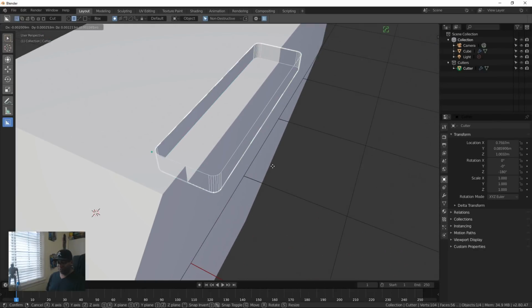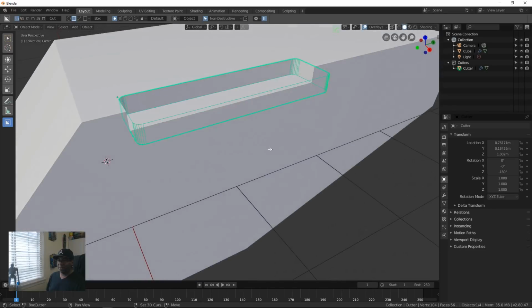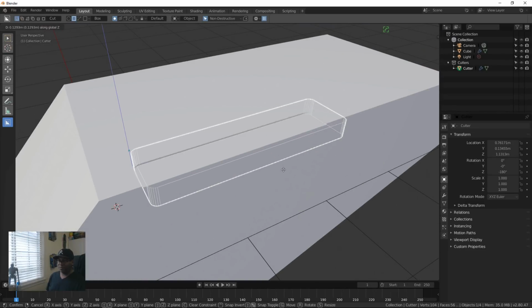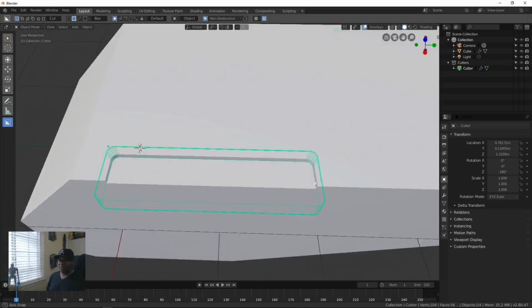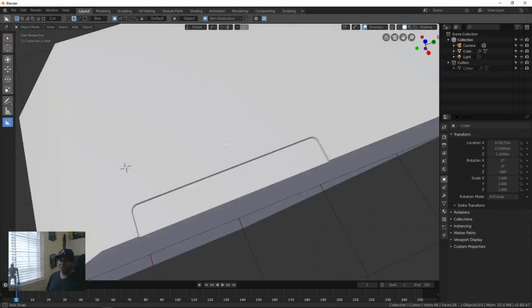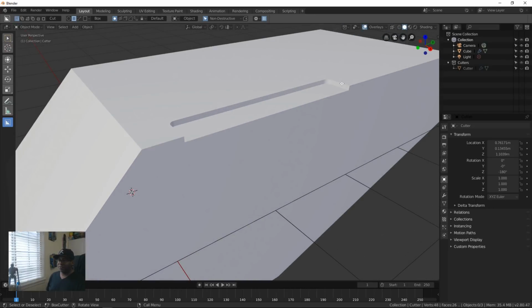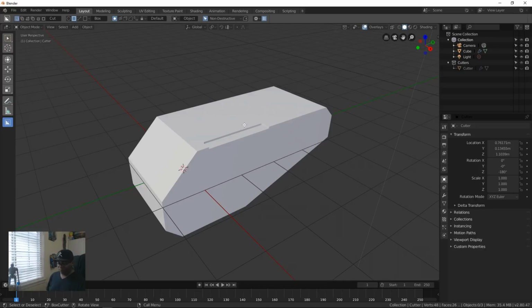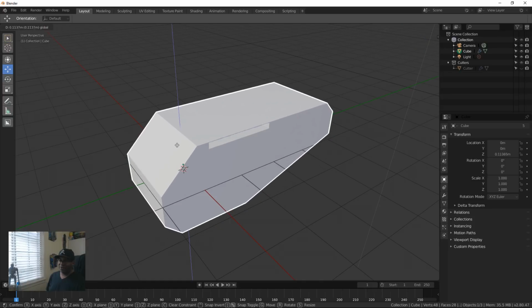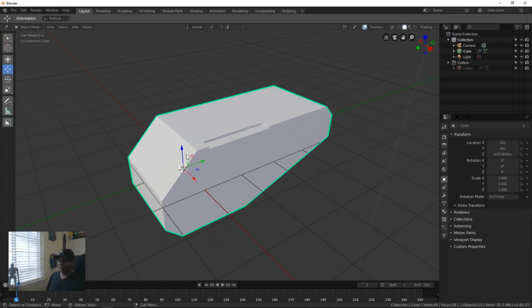And I can actually change this. If I wanted to move it around on the y-axis, or move it up on the z-axis, and just make a small light impression, I can do that, and then hit H to just hide the object. It's not gone, it's still inside of here, and I actually don't want to move this object here. Say if I grab the main object and I start moving it around, that other object is still non-destructive and live, and therefore it's not going to move with this. So I would actually have to Alt-H and show it, and then start to move this around, or move both objects together, right?